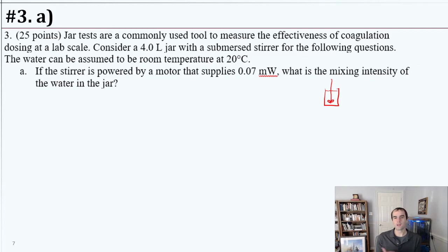every time. And so to optimize your coagulant dosing, a very simple way to do it is to take a series of jars and test different doses of your coagulant to see which one works the best, and then you just use that one for the day or for the next few hours. So operators will have a good idea of the range of coagulant dosing needed, but given the daily and hourly changes in water quality, they'll be checking it to make sure they're using kind of an optimal amount.